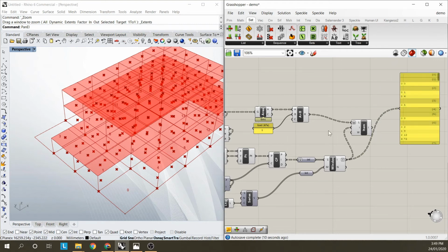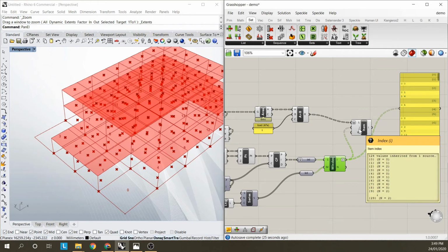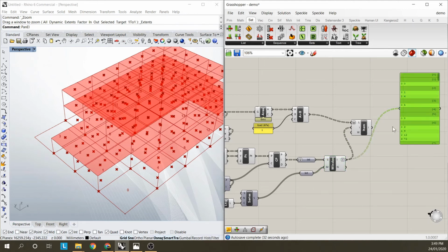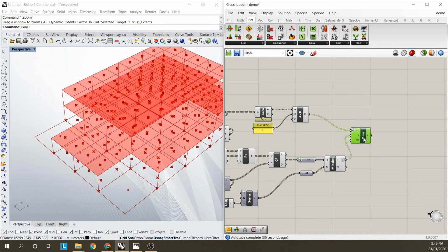and you can see that this index number goes up to about 124. So I won't go into that right now, but whenever you use list item or member index, it's really important to think carefully about how many items are in your list, how your index is related to that list, and whether they're in the right ranges. Just delete that panel. So I know this is right because I've done this before, but sometimes you have to think that through.